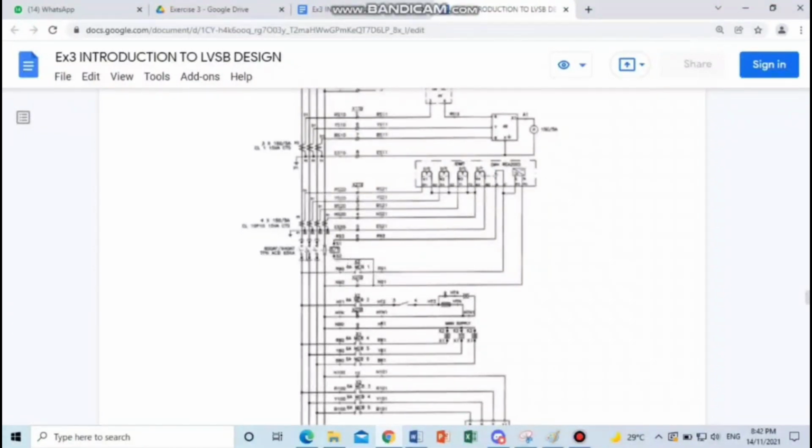This one is the ACB, which stands for air circuit breaker. Okay, it has three phases here, and it will connect to the relay. Here is the relay, and this air circuit breaker is also related to the fuse. Okay, for the relay, it will step down to 5 amp because it cannot take the high current. Okay, so here is the CP.